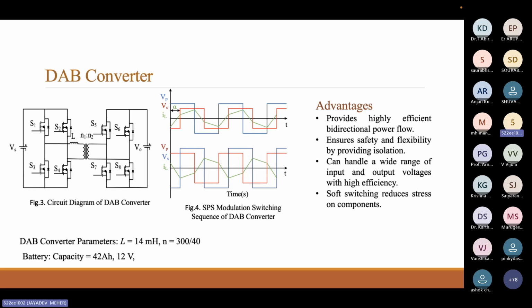And in the second case, the reverse. We change the alpha. In the above case, consider alpha is positive, and in the second figure below, we say alpha is negative. There is some mistake in the figure, so forget the figure. If alpha is negative, meaning the primary is lagging compared to the secondary, then power will be transferred from the secondary to the primary.